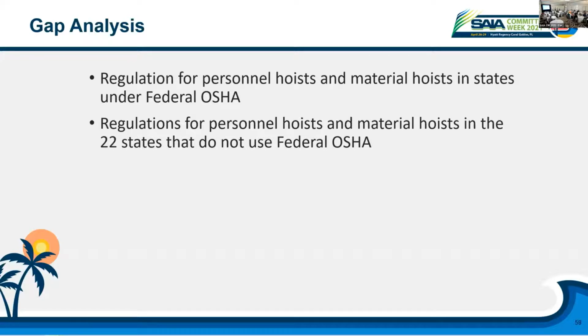Oh yeah. So for the longest time, we look at 1926.554(c)(1), which is the OSHA regulation that says all personnel hoists should follow A10.4-1963.